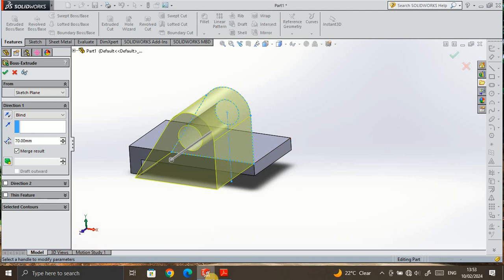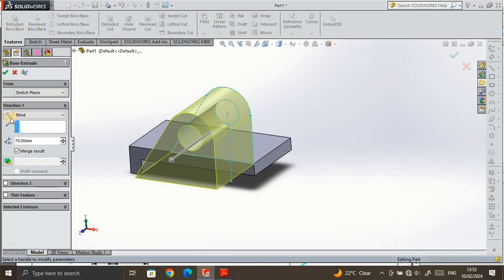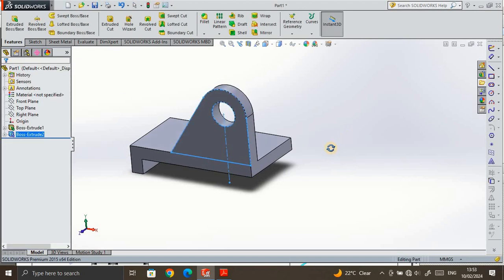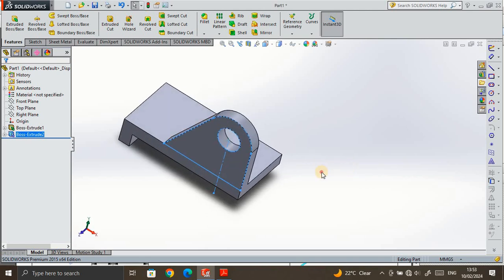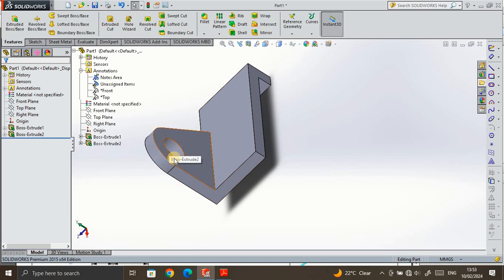So total thickness we can see 12 mm is given. We can see in the top view of the 2D view. Reverse the direction and put the value 12 mm. Press OK. Exactly aligned vertical plate, but the internal ring remains.